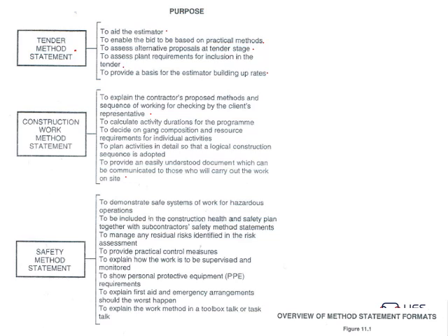Okay, so that's the other thing that we haven't spoken about, is actually conveying the method of construction to your team on site. When you've got your toolbox talk and you need to convey that information to your team and to your managers, you can actually have that method statement that you can give to your site or your foremen, and or explain it in the toolbox talk. Okay, so you've got a document that you can work from.